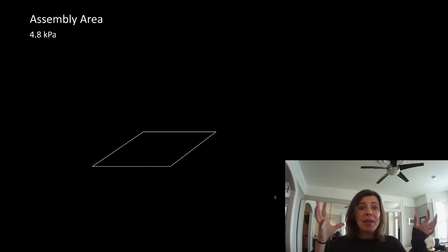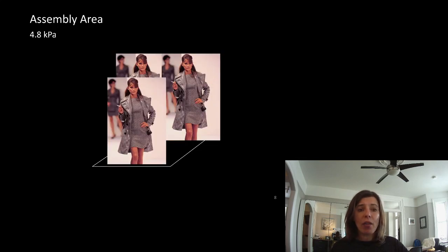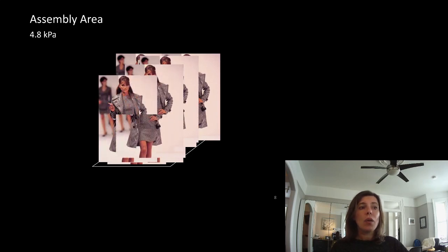And Arnold's got a really tight body mass index, there's a lot of weight packed into one small package there. We've got our half a kilonewton model. We need 9.6 of that model to give us 4.8 kPa. So that's a lot of people crammed into a 1 meter by 1 meter square.